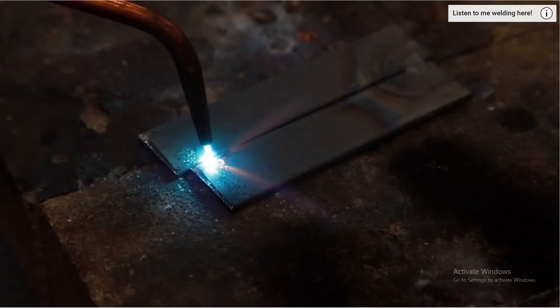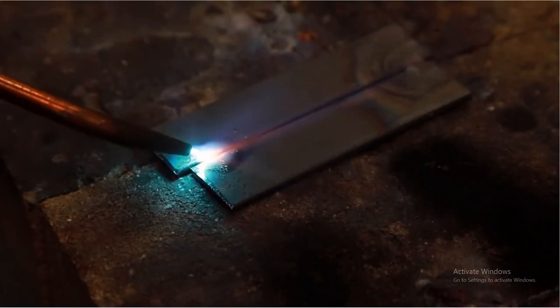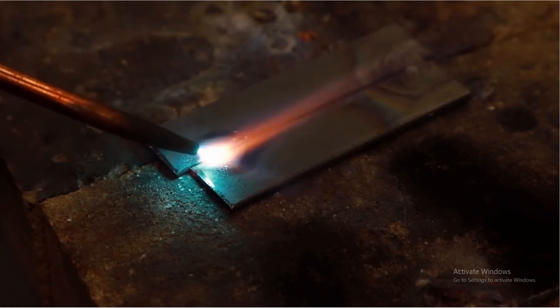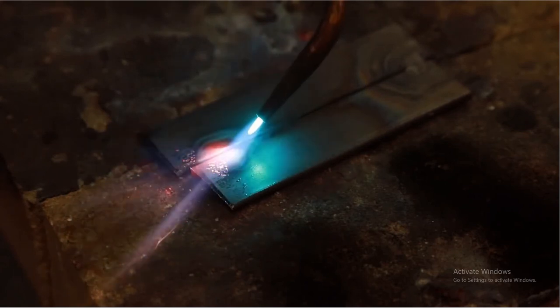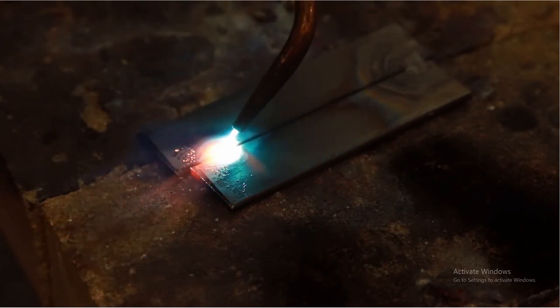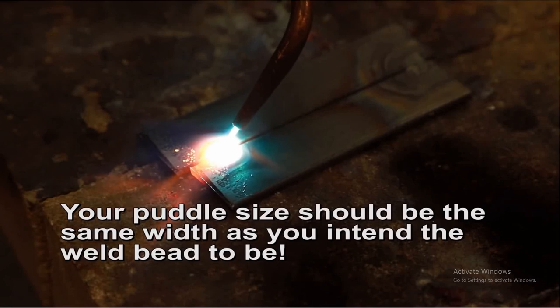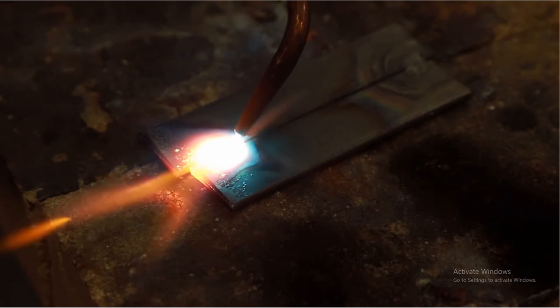I've dropped the exposure on the camera so you can get a better look at what's going on here. So I'm holding my torch on about a 45-degree angle, zigzagging back and forth between the two pieces. I'll hold the torch on the other side so you can see better, and I want to get a nice little puddle going. Back and forth between the two. And I'm just hovering above the metal. I don't want the torch to actually touch the metal.